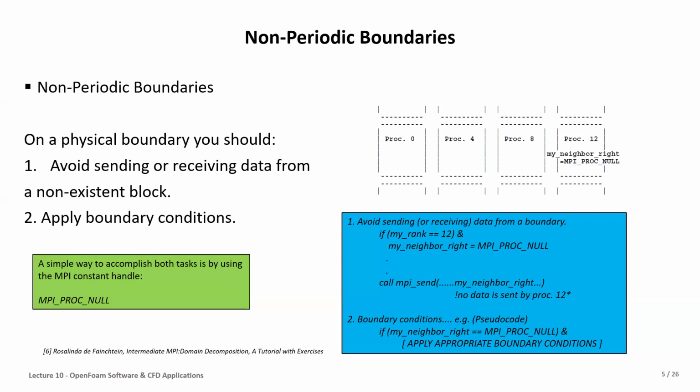Since in a CFD problem we are dealing with boundary conditions, and one of the important parts of the required information for a CFD problem is the boundary condition, we need to choose the correct way in the MPI setup to explain and define the boundary information for the domain and the subdomains to get the correct solution.